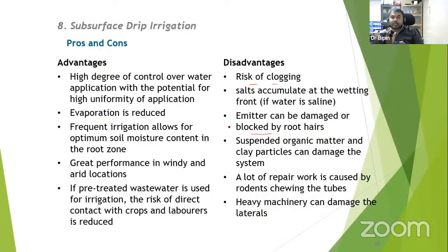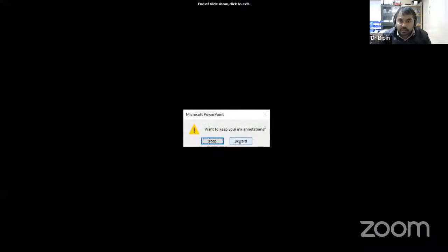When algal growth increases, it will block your pipe emitters. That's why we need bleaching of our pipes, so that the algal growth can be reduced. Chlorine is one of the most commonly used chemicals for cleaning the drip system.